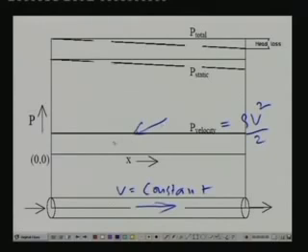And if the fluid is ideal, then the static pressure also remains same. So, this is the static pressure line for the ideal fluid. Since the total pressure is summation of velocity pressure plus static pressure, the total pressure line is also horizontal. So, total pressure at any point is equal to velocity pressure plus static pressure, and it remains constant throughout the length. So, this is the application of Bernoulli's law to an ideal fluid.